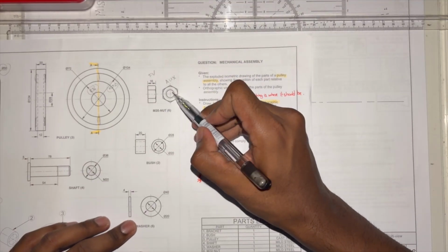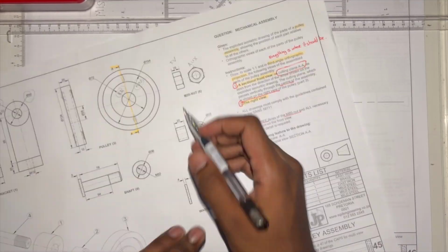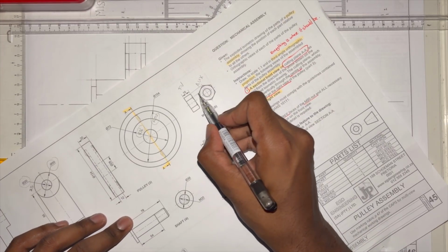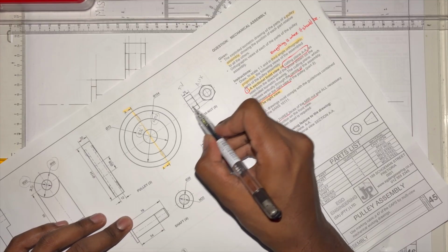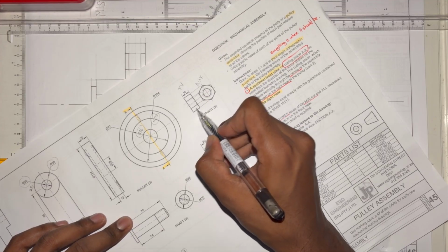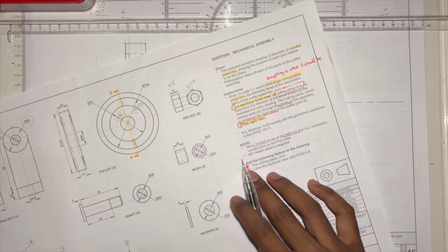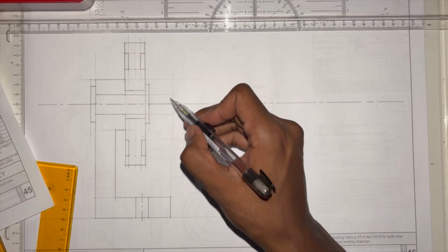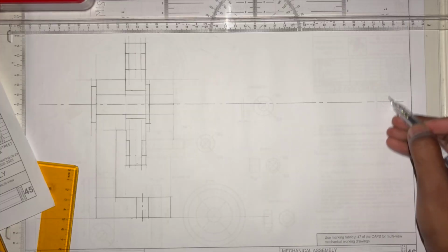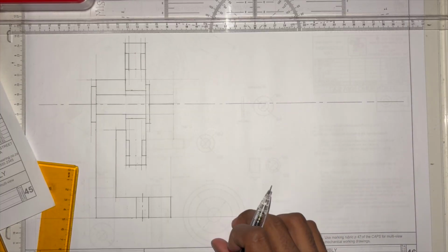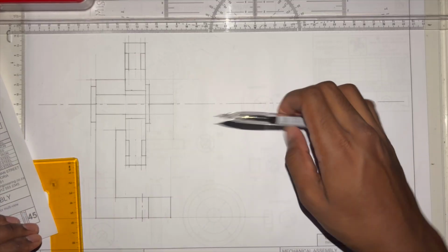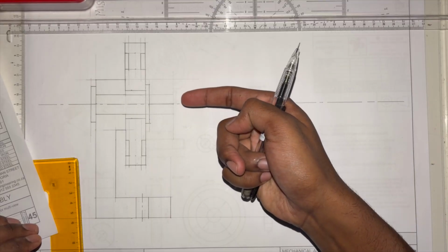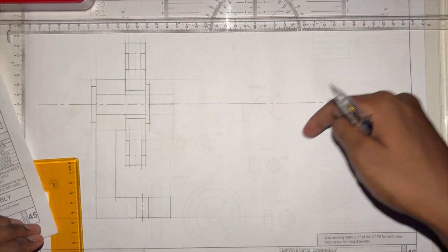Of the nut. Now, we need to draw this in order to project those lines back, and then those 2 circles come to get the shaft. You need to draw this to get that. Where do you draw this? That's the question. Do we draw it here? Do we draw it there? Do we draw it here and then just project that there? Here's the thing. Now we need to draw a right view, which is looking this way. The right view is going to go on this side of the page.